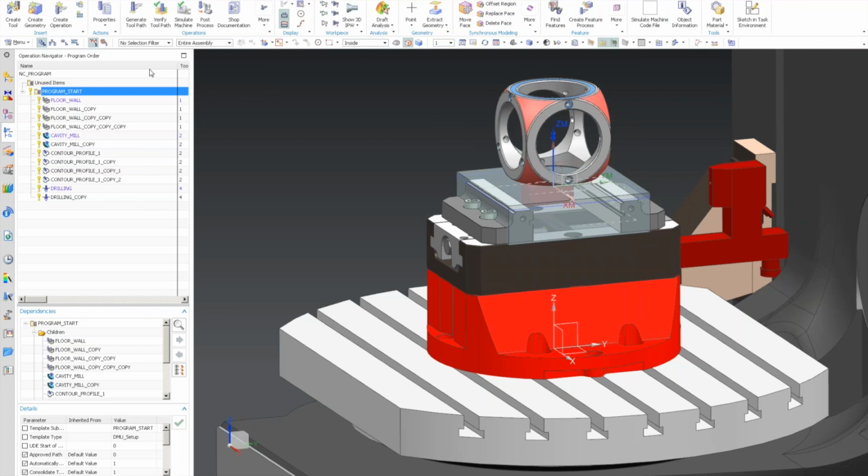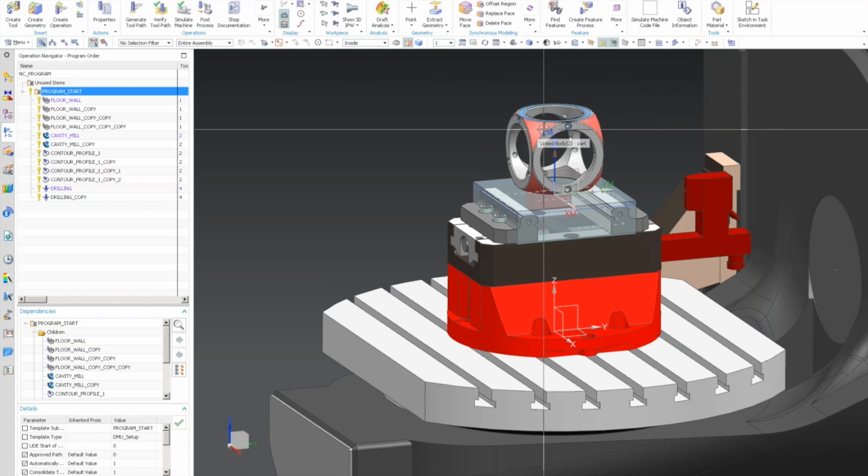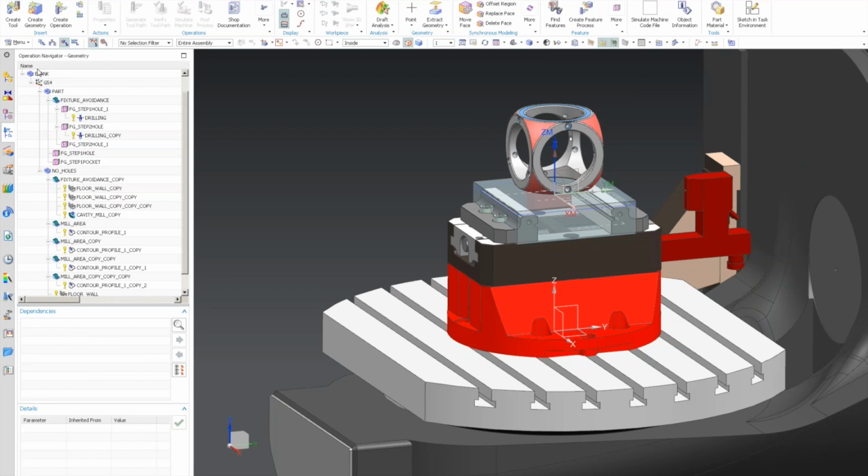Of course, you can add more. If you have certain operations or toolpaths set up the way you like, it can bring all of those in, and then you basically just tell it what your part is. You pick your part and you pick your stock, and every toolpath is going to look at that. It just inherits it, is what NX is basically doing.